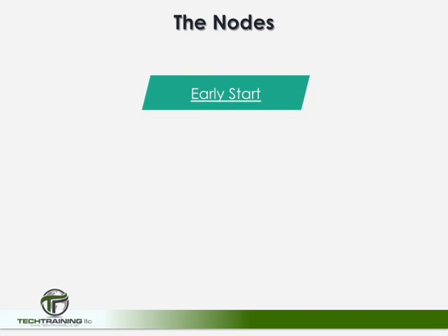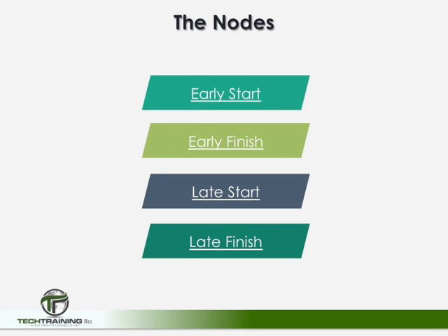Now these activities are placed in the schedule in diagram form and read left to right. The nodes have varying information in them. As an example, most will have early start, early finish, late start, and late finish. These items will also be represented by dates, or in some cases simply numbers, which represent working days or calendar days.